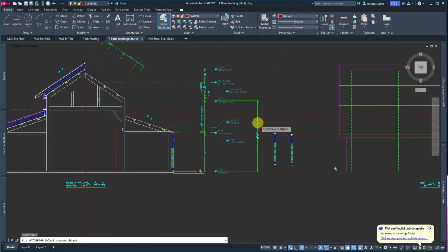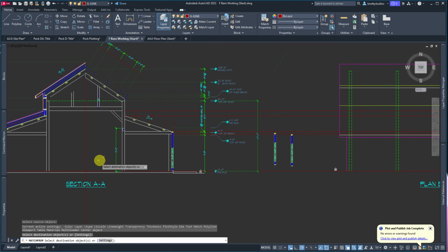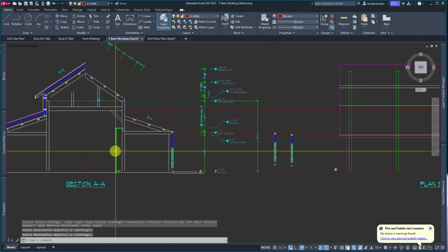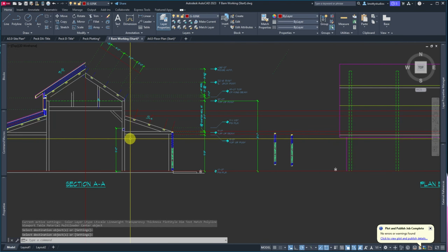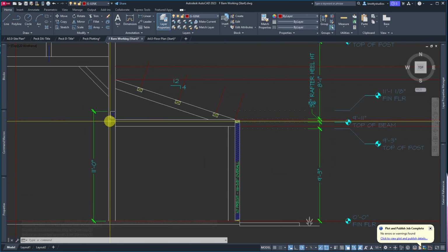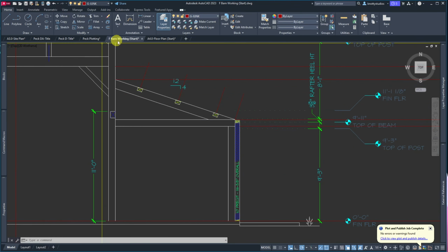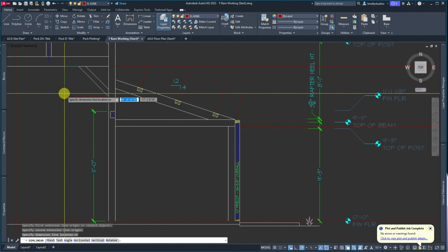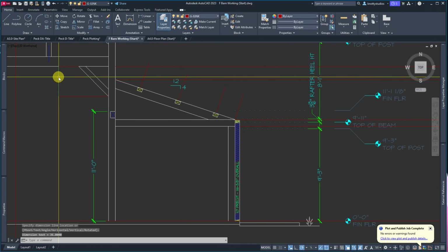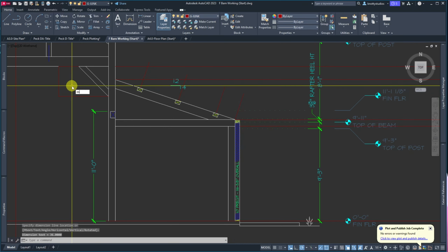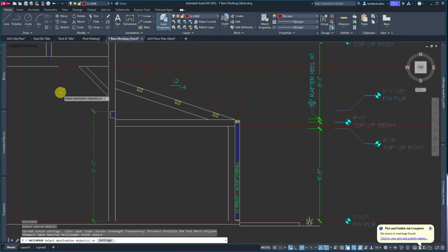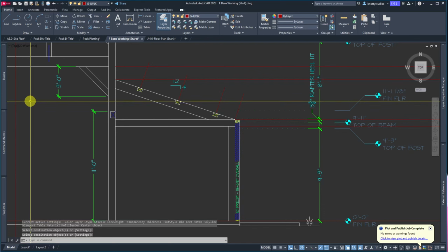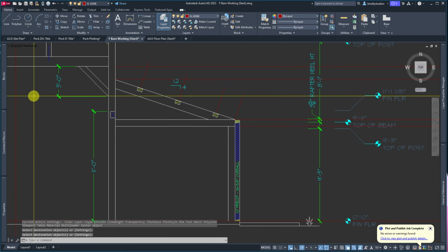So what I want to do is match properties on my dimension style and put that there. There's the 11 foot as he has it drawn, and then back down 8 inches, and it doesn't work. So here, he has this dimensioned out, and I'll just do MA, dimension that. You can show he has that the way he wants it.